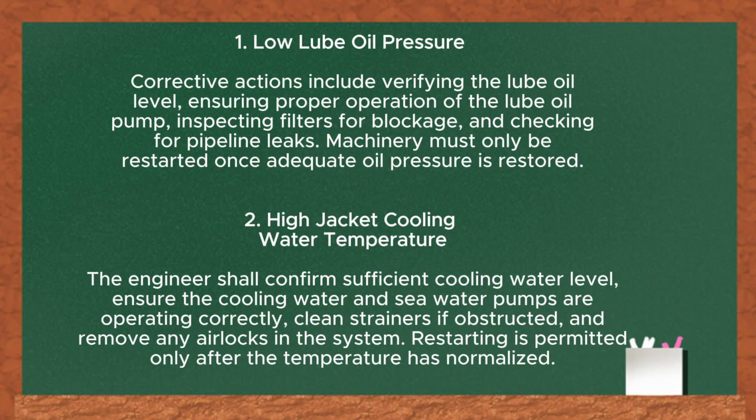Number 2. High jacket cooling water temperature. The engineer shall confirm sufficient cooling water level, ensuring the cooling water and sea water pumps are operating correctly. Clean strainers if obstructed and remove any airlocks in the system. Restarting is permitted only after the temperature has normalized.